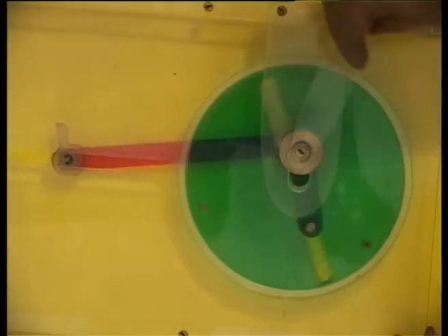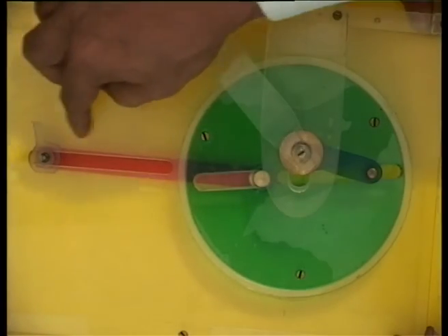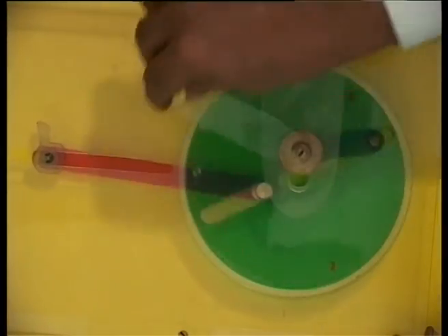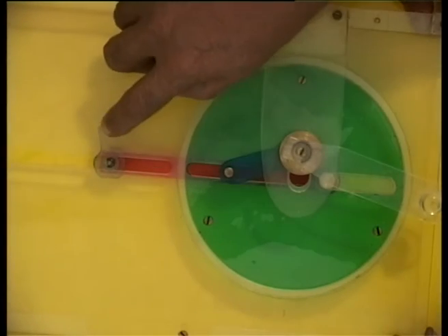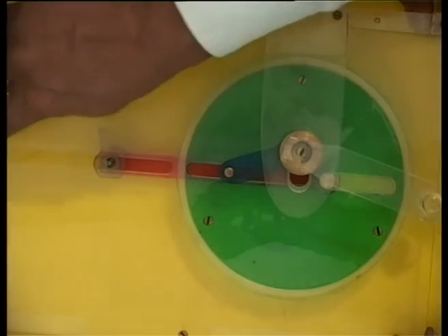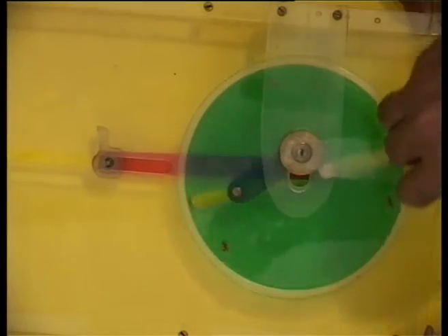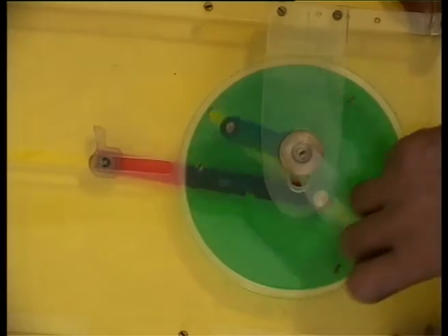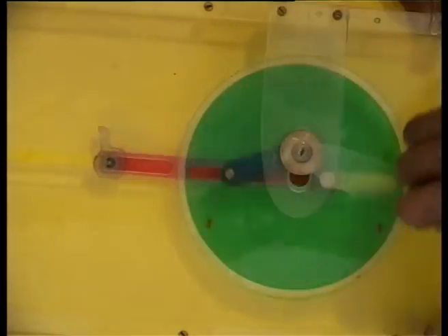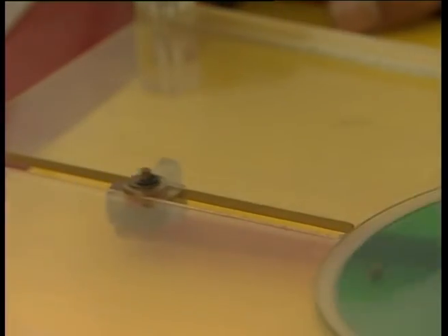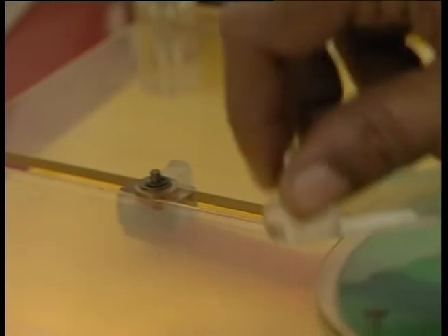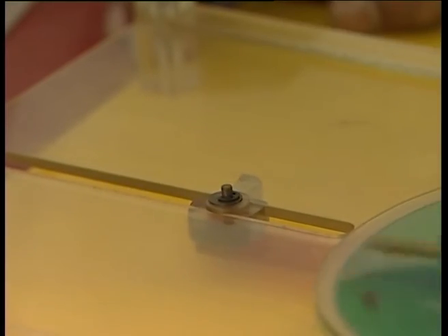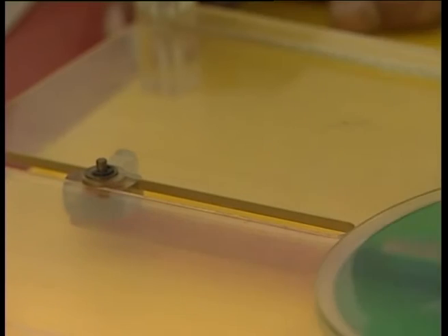It is going much faster in this direction and coming back much slower in this direction. So, if we consider this as the cutting tool which is cutting in that direction, then we should rotate it in the opposite direction. It is cutting slowly and returning much faster. Next, we shall see the kinematic diagram of this Whitworth quick return mechanism and analyze its quick return ratio.